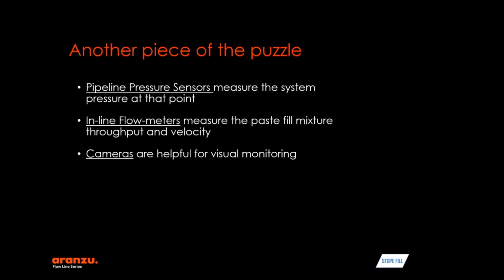This is a key part in knowing when to apply the compressed air flush, in that you actually have mobilisation of the paste fill material before applying the air flush. If applied before the mobilisation, it can cause further compaction of the blockage paste fill mixture in the pipe.